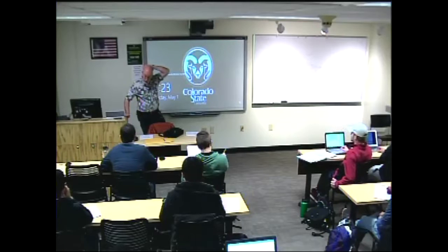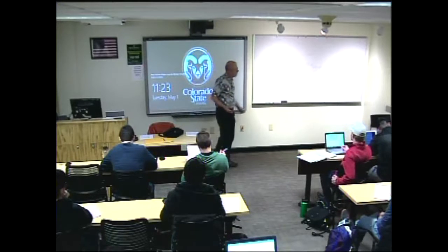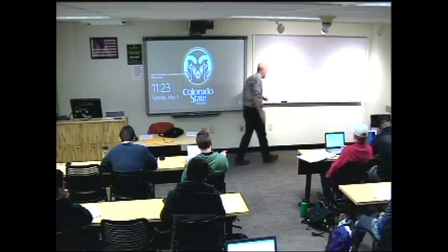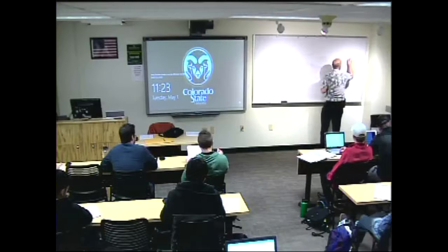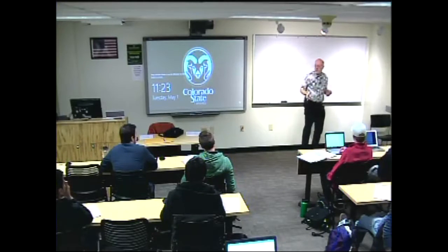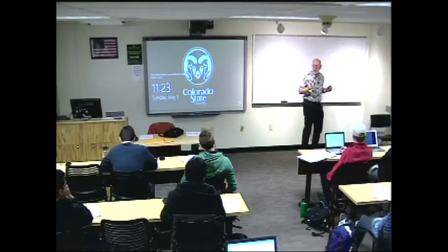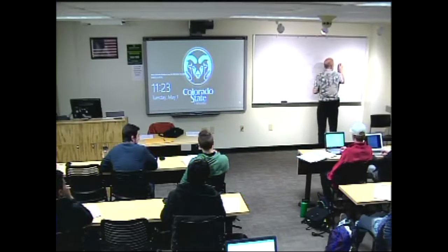And then, because a million or whatever it is was not a high enough signal-noise ratio, I'm being sarcastic here, I decided to have you filter it so you could get a higher signal-noise ratio. And you calculated some filter bandwidth, and then to figure out how to relate, if I have a simple RC filter, there's a formula in there that has VC minus VN.